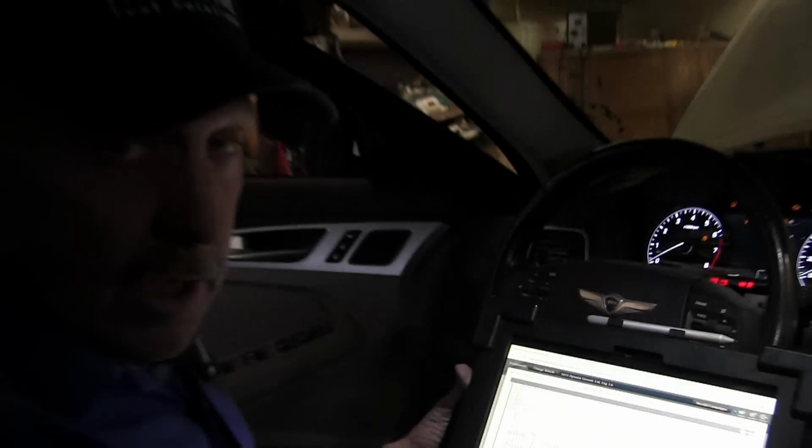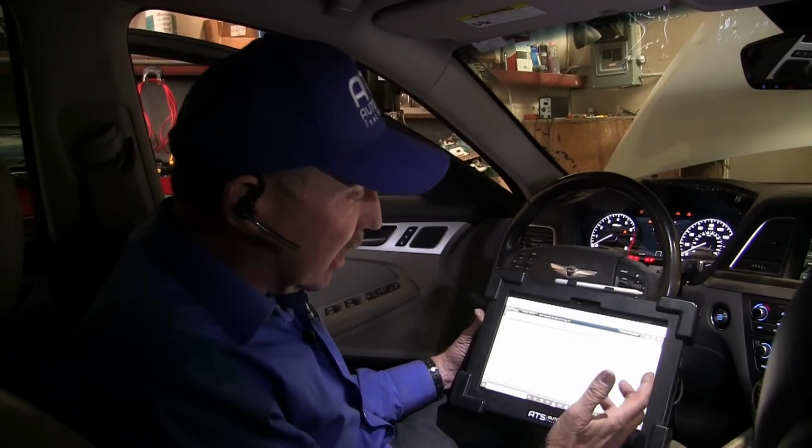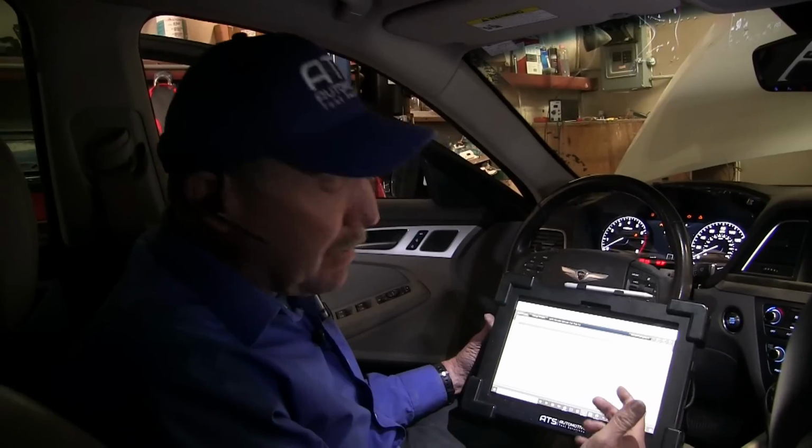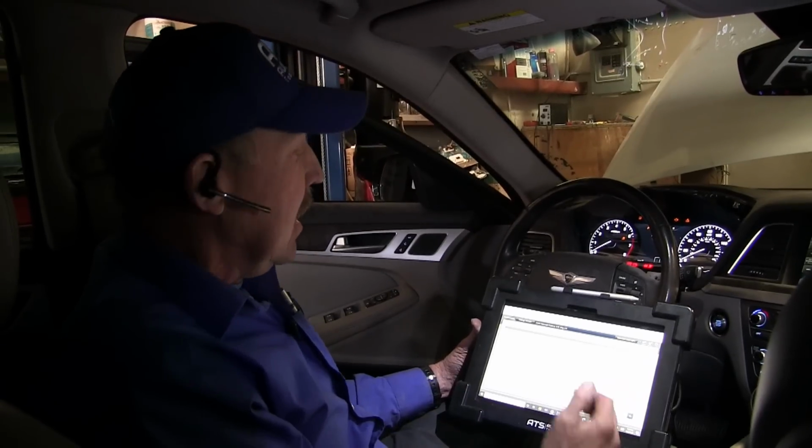Now what I've seen by going through this data right now and the way that the topology is laid out is if I put a breakout box and I go through the DLC, I will not be on the bus that I'm concerned with. I'm on CCAN. I need to be looking at a CCAN bus. The wires that come out of the DLC are how we're communicating, and we already saw the scan tool can communicate with the bridge or the gateway.